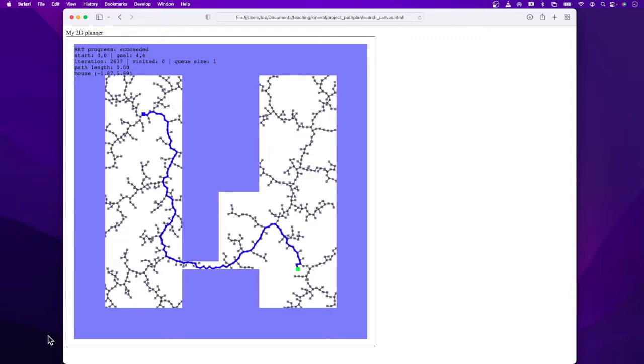All right, so now we can see, at the very end there, it was able to sample a point that led it to extend the tree within an epsilon step of the goal. And so you can see at that point it was able to trace back the path all the way to the start node, which was then through this blue highlighted sequence here.